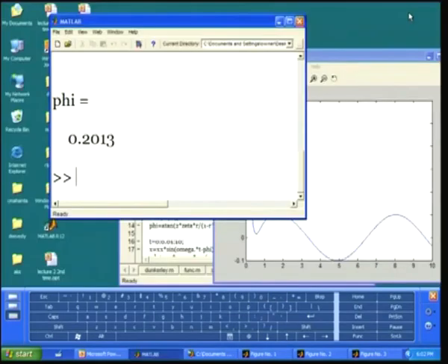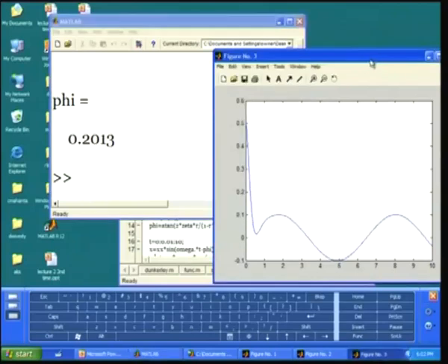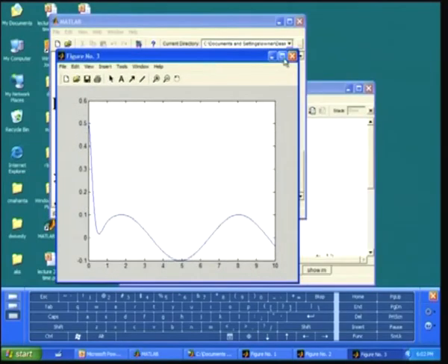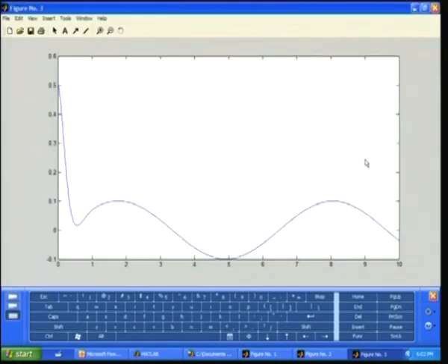Also, I obtained the same thing by solving it with the Runge-Kutta method. In this case I have taken only a single frequency, f sin omega t. You can see that the initial part is the transient response, and after that you have the steady state response.